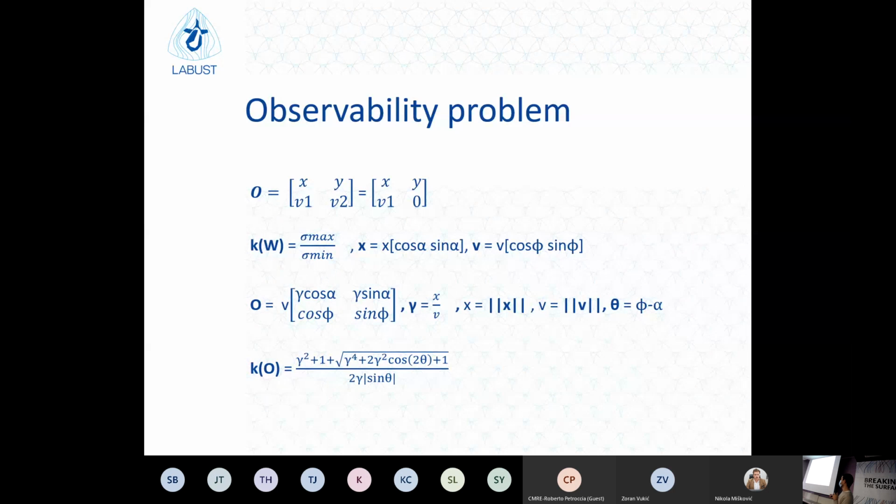As you can see, it has two speeds right here. The first is the speed of the vehicle, and the second is the speed of the beacon from which we range. As in most cases the beacon is static, we need to ensure the vehicle is in constant motion to ensure that we have observability.